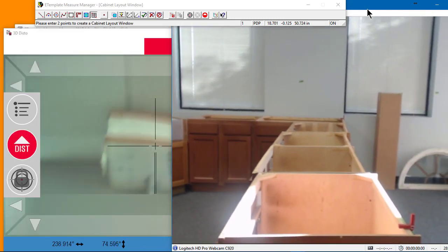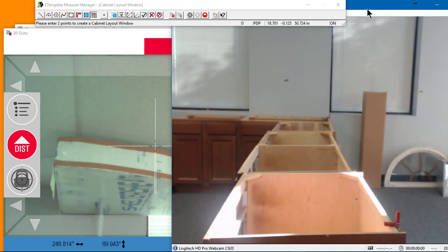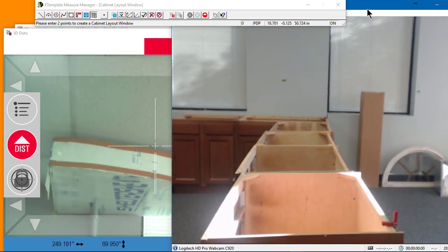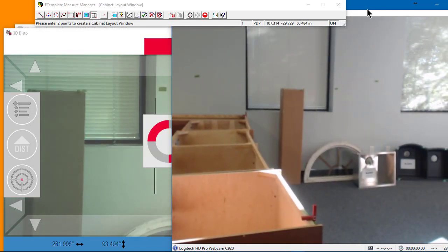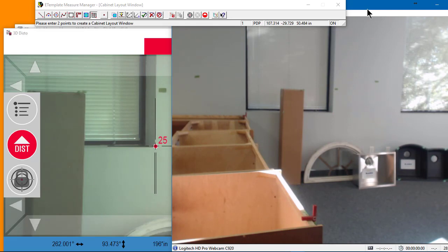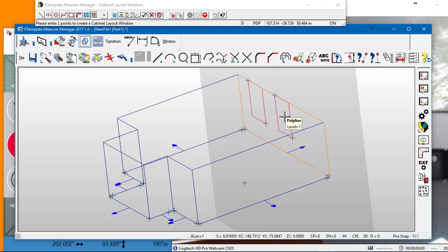Now in this case, I can't quite see that window because there's this soffit thing in the way. But since this is a planar geometry and that back wall is the construction plane I'm working on, if I hit a point on that ceiling, I'm standing where I can see directly towards that window, and I can shoot that point and it will drop to the wall. And then I can shoot this point down here. And let's take a look at our drawing real quick so you can see what's going on there. So you can see I've got both these windows put up.